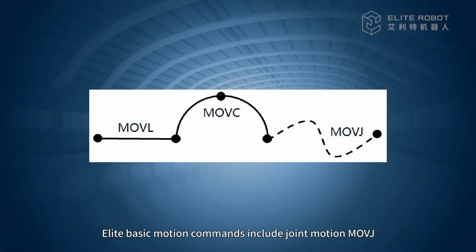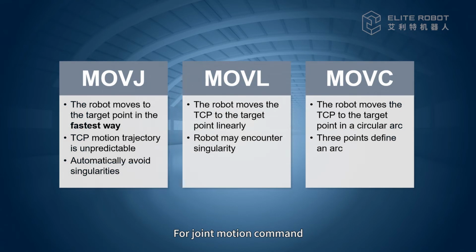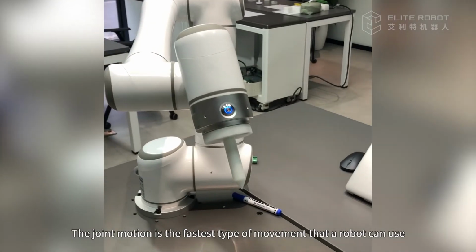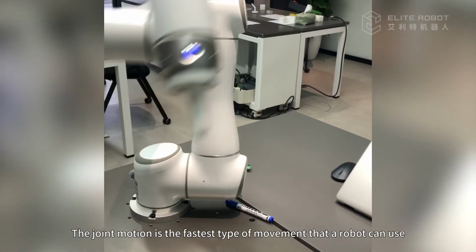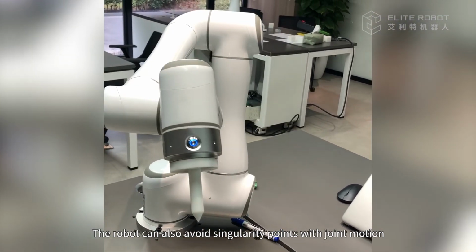Elite's basic motion commands include joint motion, linear motion, and arc motion. For a joint motion command, the robot will execute the motion by joint interpolation. The joint motion is the fastest type of movement that a robot can use. The robot can also avoid singularity points with joint motion.